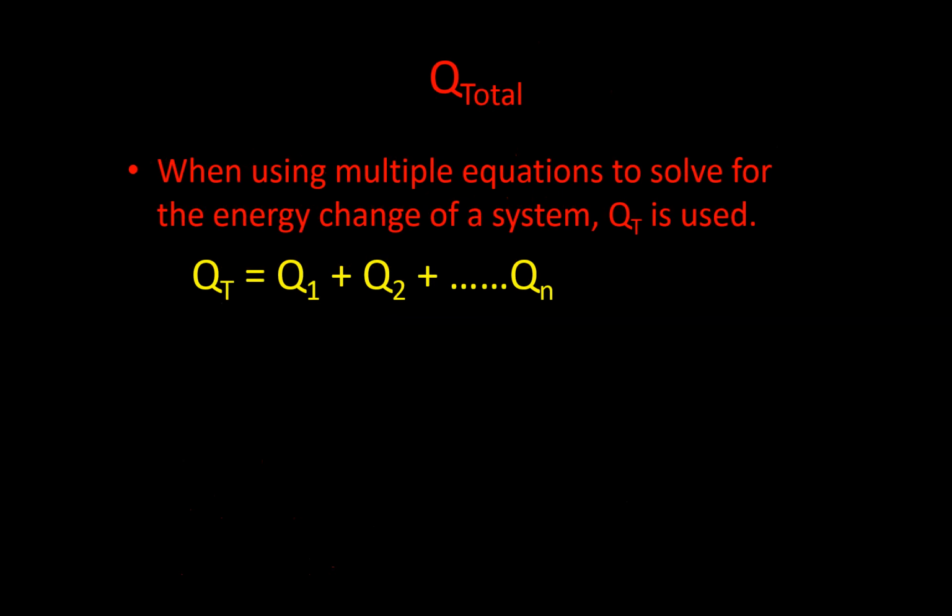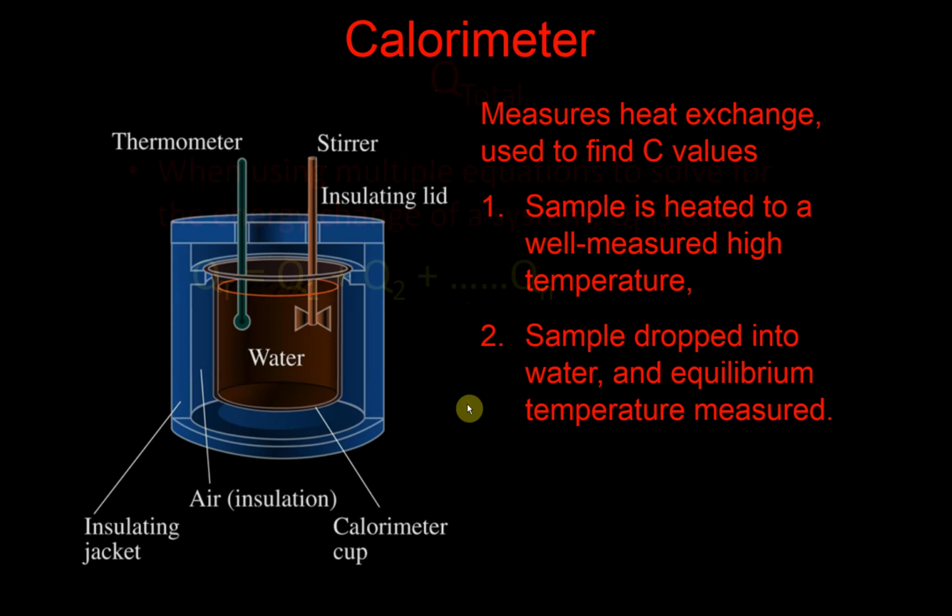So in some cases, if you're using multiple materials or multiple energy sources, you can calculate Q total and add up MC delta T for all sorts of different materials, especially when you're looking at calorimetry and you're dropping, say, metal into water. You could do Q equals MC delta T and equate that to Q equals M times LF or LV for your fluid. And you'll often see this kind of thing done in a lab. And this is what we mean by something like calorimetry.